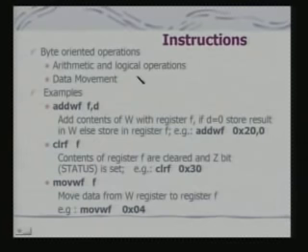Let us first look at byte oriented operations. These byte oriented operations are primarily targeted for arithmetic and logical operations as well as for data movement. We have shown some examples here. These instructions, ADDWF F, is an instruction for addition.